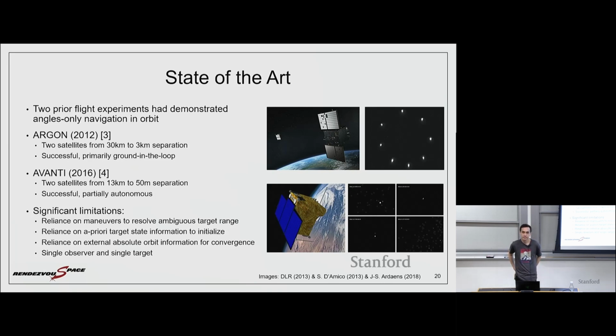Yeah. Very involved, the mission operation schedule. Basically, we were a team waiting for a ground contact to happen. During the ground contact, all the images that had been collected by the spacecraft were downloaded to the ground, and then we started running our software, which was image processing to extract the bearing angles, and then orbit determination, and then maneuver planning, to plan the maneuver commands to be sent to the spacecraft at the subsequent ground contact.